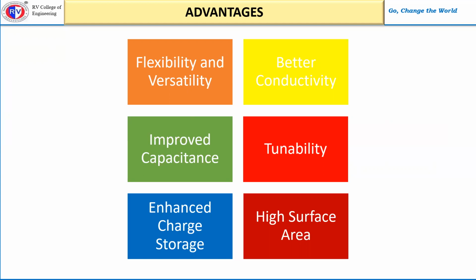Coming to better conductivity. Here, the nanomaterials possess excellent electrical conductivity, which promotes efficient electron transfer within the electrode material. This facilitates faster charge and discharge rates and reduces the overall internal resistance of the supercapacitor, enhancing its performance.